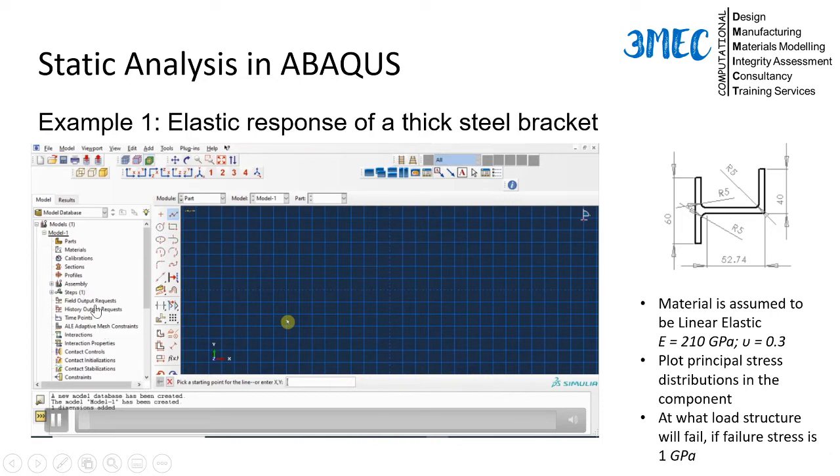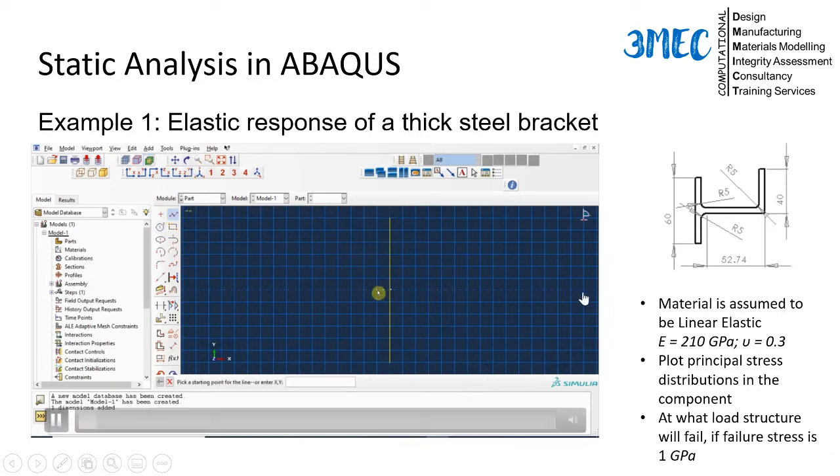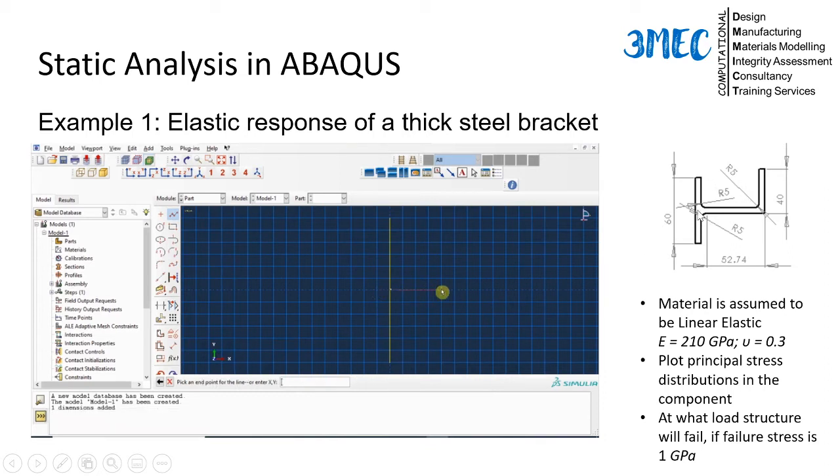So I'm still thinking, you see, there's a thought process behind it as well. Again, there could be many different ways. Another way could be to find these coordinates based on these dimensions, and then just draw lines and use trimming and filleting to create these fillets around here. So I'm drawing the center lines right now. So this line, then this line, and then maybe this line. I'm trying to work out the coordinates based on the dimensions given to me. Again, when my mouse is not working, this means I'm trying to calculate this.